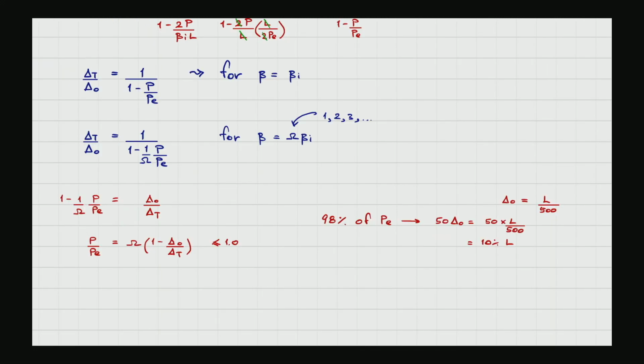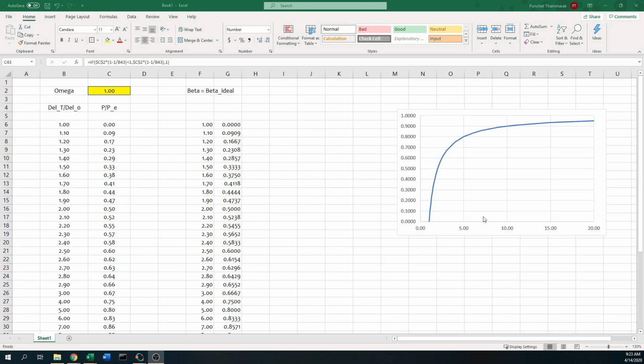Your column is, let's say, 3 meters. In order to mobilize to 98% of the expected strength, you need to let the brace move to 10% of the length of the column, which is 30 centimeters. That is going to be ugly. That is going to be really, really ugly to have the system deform by as much as 10%. And I'll switch back. So this one here is ineffective.